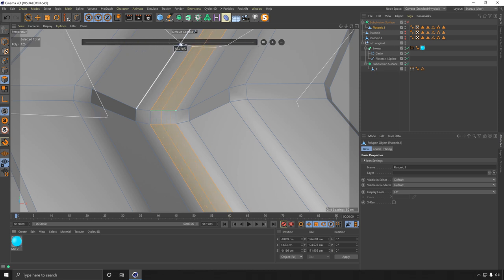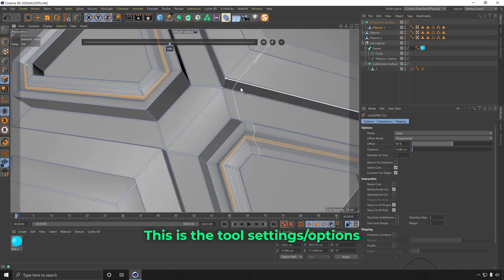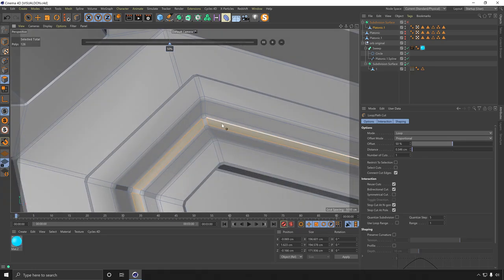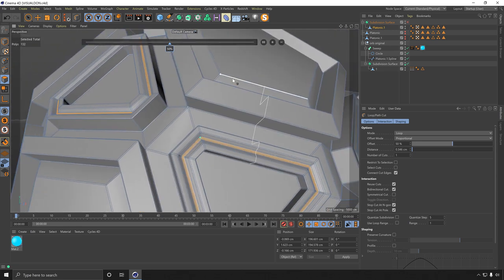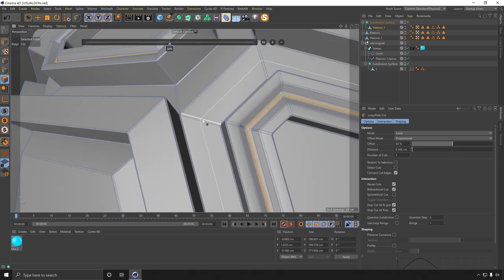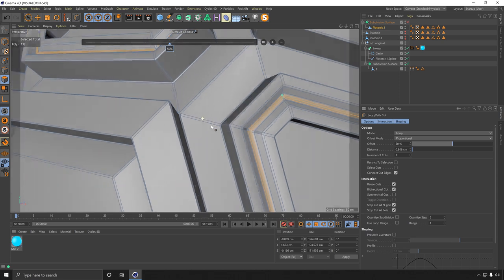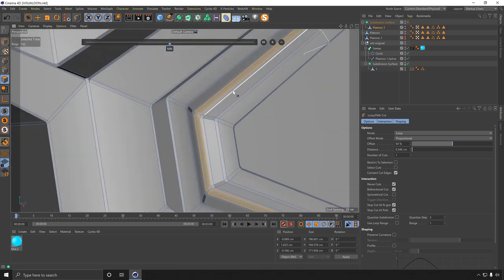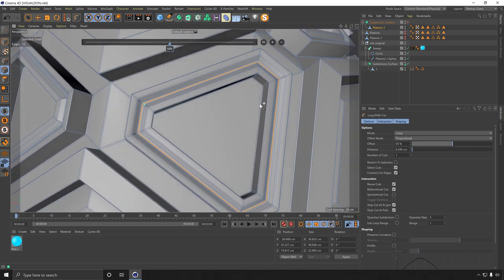Now here is something else, which is I can reuse the cut because the first one was made at 50%. And I want to repeat this on all of these other sections. And you see now with reuse ticked, it's always going to snap to 50% of where you're trying to make the next cut. And it doesn't matter where this is, by the way. So it could be here, it could be there, anywhere we can make a loop cut. If we reuse it, it's going to be using the same proportions as the previous section. All right, so I'm just going through these one by one.